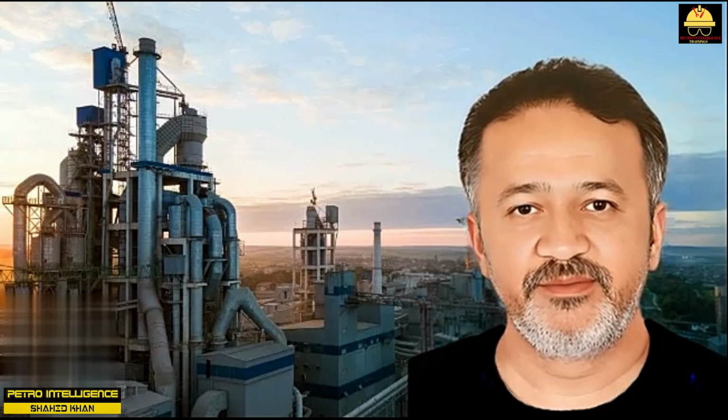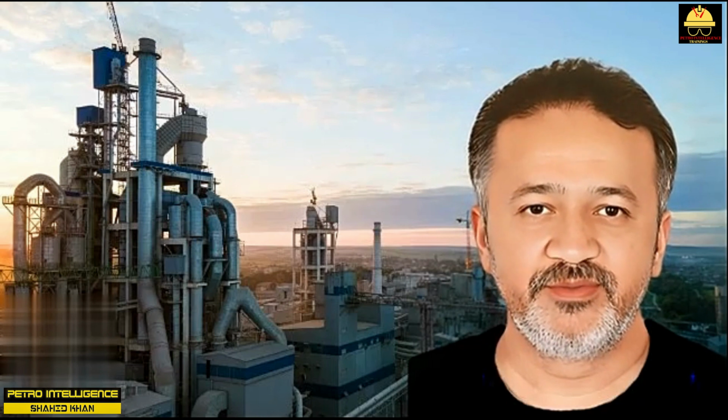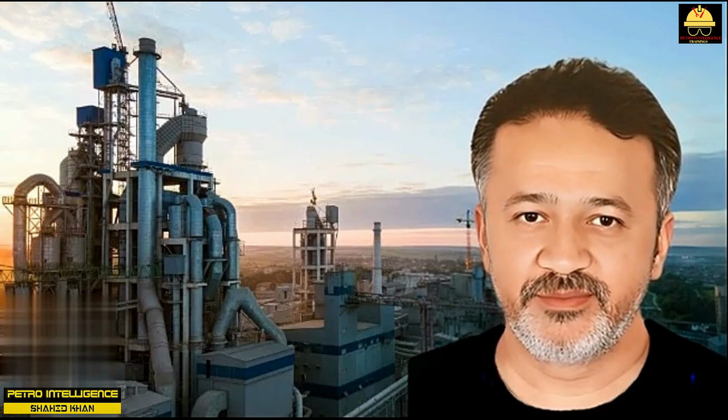Importance of shell-side cross-flow. Shell-side flow should be mostly at right angles or perpendicular to the tubes. Unavoidably, as the fluid flows from the inlet nozzle to the outlet nozzle, there is some component of flow parallel to the tubes. The bigger the tube support baffle spacing, the greater the component of the flow parallel to the tubes. A larger baffle cut also increases the component of the flow parallel to the tubes.